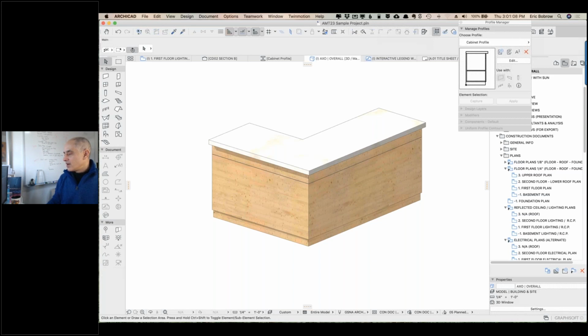All right, so Chris says, I might have a brick wall with a rendered wall above it. When I put a door in the brick wall, it only cuts through the brick, not the rendered part. Okay, I'd have to see the context for it, Chris, to be able to help you with that. If you do have two stacked walls and you want the door to cut through the upper part, then you'd probably need to put in an empty hole in the secondary part to be able to see it.